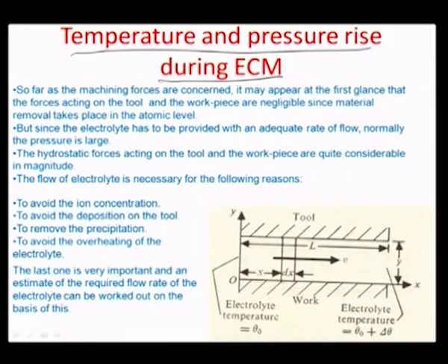And as we have already mentioned before, as far as machining forces are concerned, it may appear at first glance that the forces acting on the tool and workpiece are negligible, since material removal takes place at the atomic level. However, you can understand that because of the very small gap y here between the tool and the workpiece, there is going to be enormous concern about the pressure and the effective force on both the tool surface as well as the workpiece surface because of the electrolyte itself.